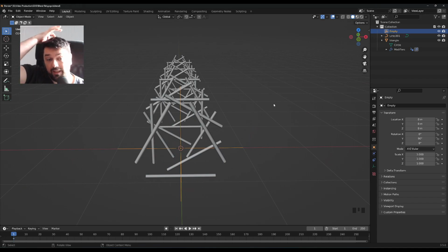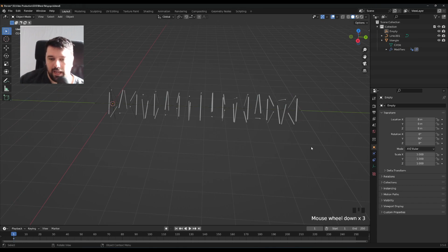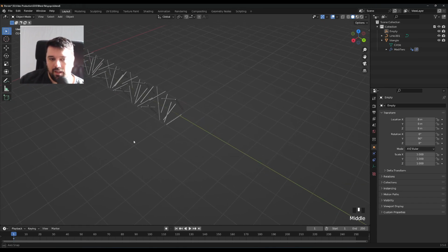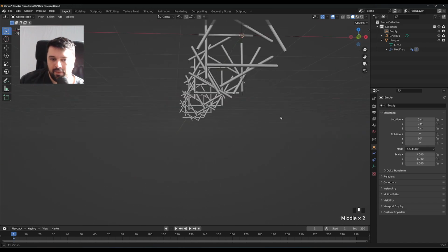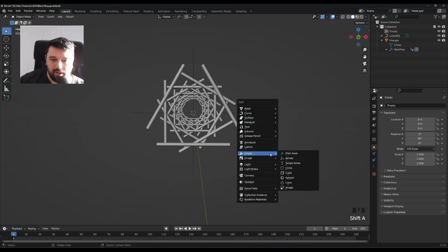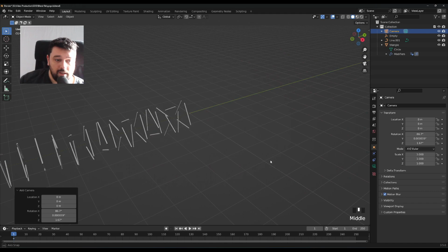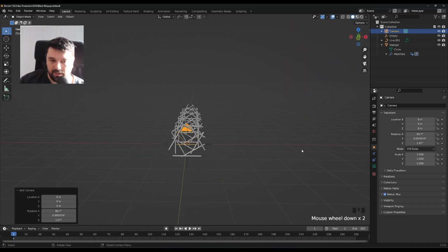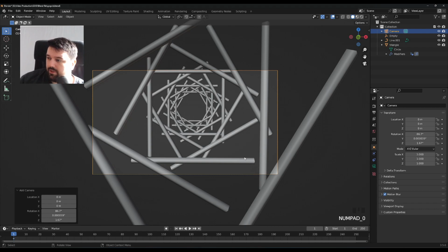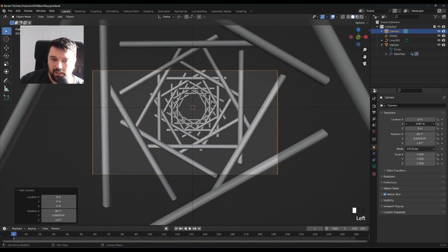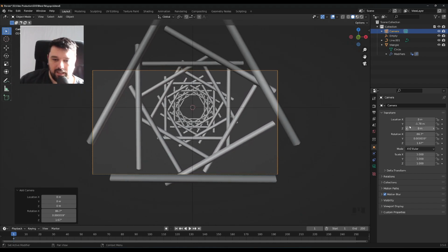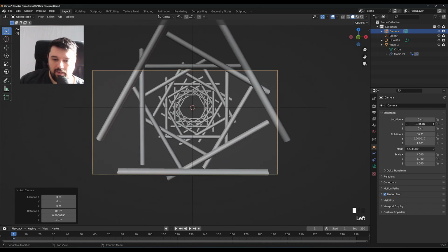So where we got to go from here is we want this to continue. We want to make it perhaps a loop in our scene. If we're doing a video, we don't want it to seem like it suddenly cuts out. So for instance, if we actually bring a camera into our scene, so Shift A, camera, and you'll notice that if you press 0 on your numpad, you'll get what your camera is looking at. So we can actually bring this back slightly. So we can start somewhere like here, for instance, could be a good starting point.